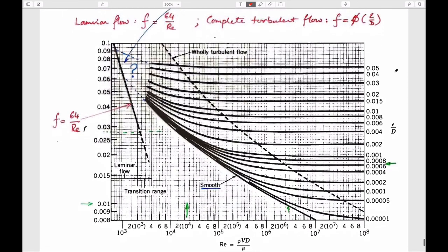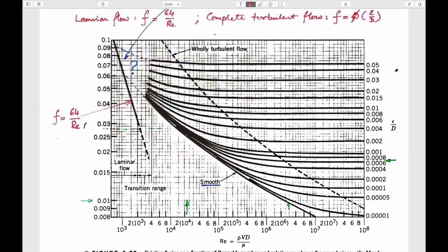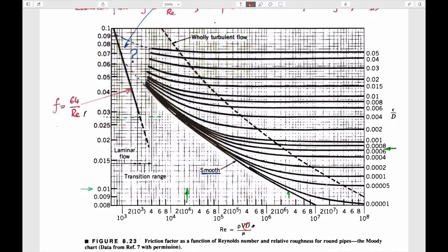Yeah, we spent some time talking about this chart. So friction factor, which is analogous to an Euler number or an inverse Euler number. Reynolds number, which is defined in terms of the pipe diameter or the hydraulic diameter. Typically around this number of 1,000 or 2,000 we've often chosen. This is 2,000 here.